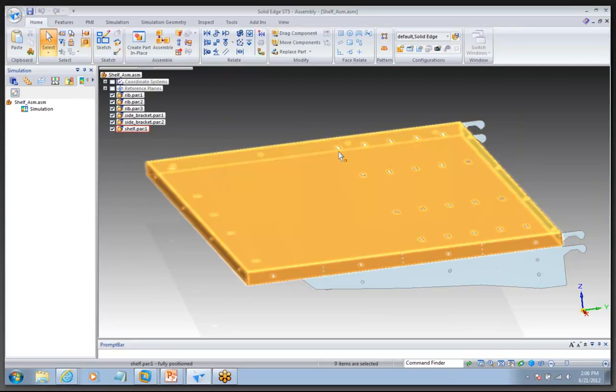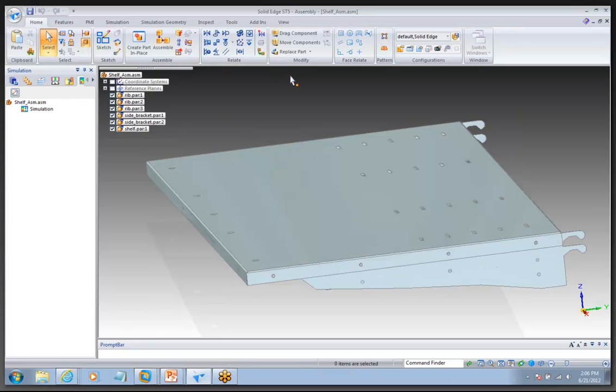So in order to get around these small features, those elements are going to have to be very small. Now for solid elements, it's a tetrahedral. It looks like a pyramid, and at all the vertices, those are called nodes. Each node can move in x, y, and z. So it's got displacement in x, y, and z. We call those degrees of freedom.